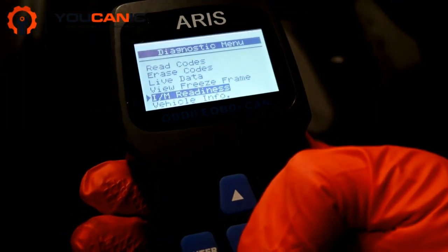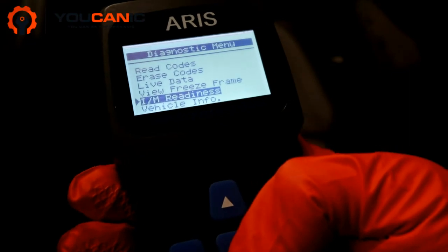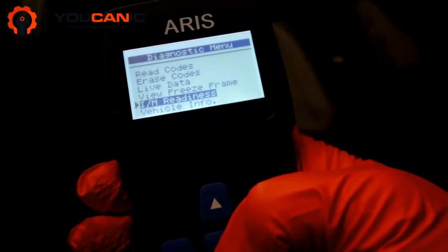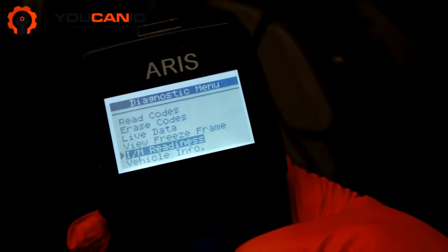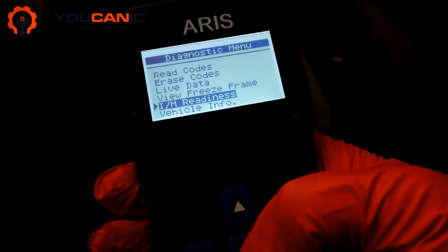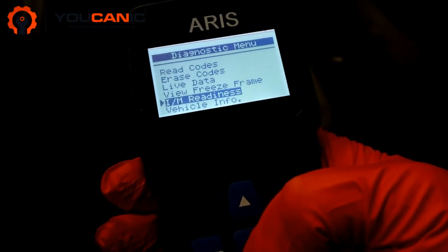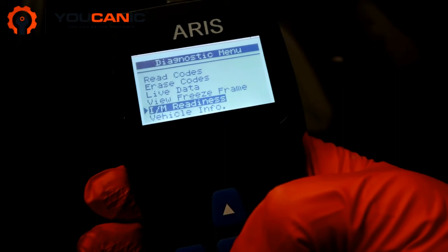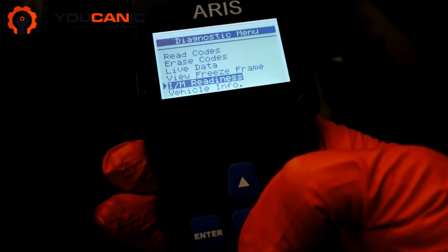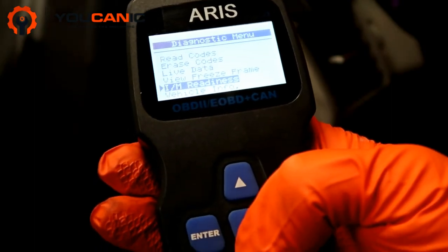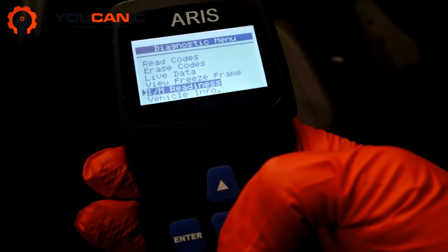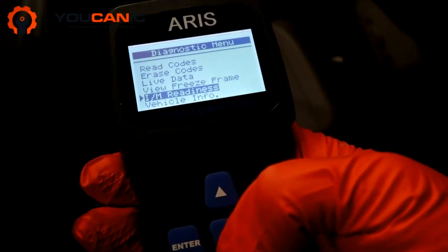It's pretty easy to access, and the part itself could be like $50 at most, versus if you go to an auto repair shop or your dealer, you're going to pay $300, $400, $500 to replace a mass airflow sensor. If you think you have a loose gas cap, you're going to get a code for that. We do have a database with all the codes and what they mean. You can simply search YOUCANIC DTC codes, but you can search those codes anywhere online.